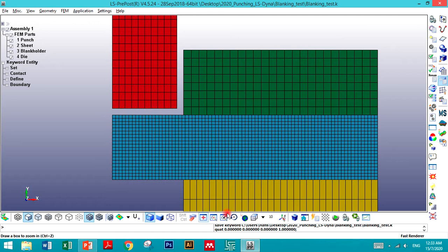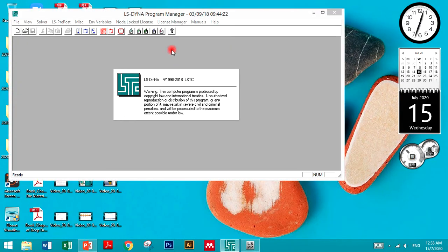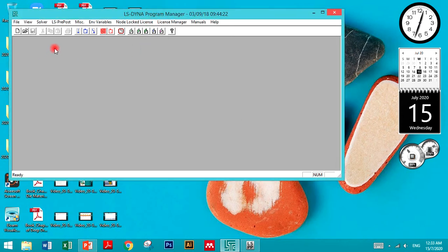Okay, how to do it? What you need to do is click on this, launch the LS-DYNA program manager, and click start LS-DYNA.